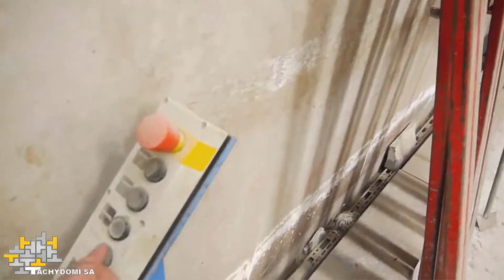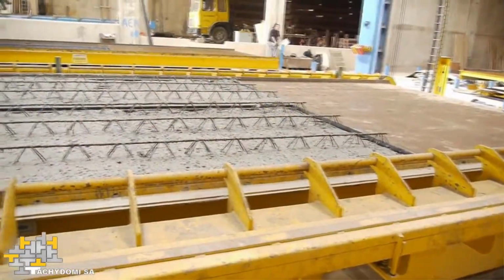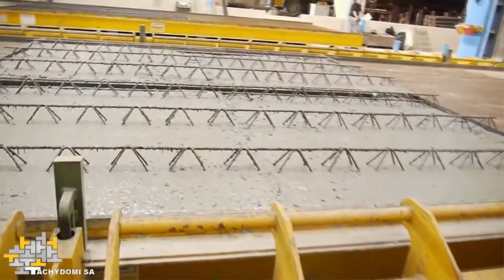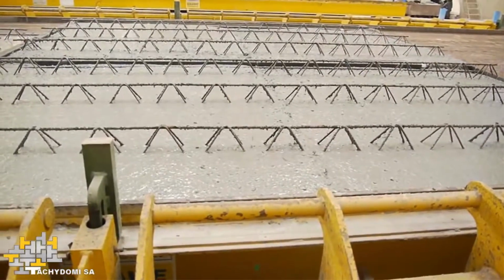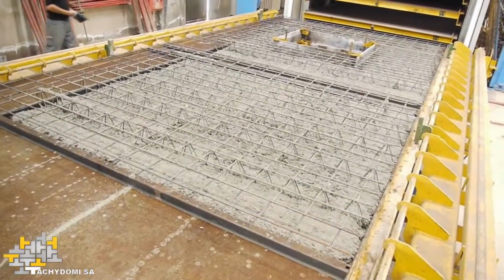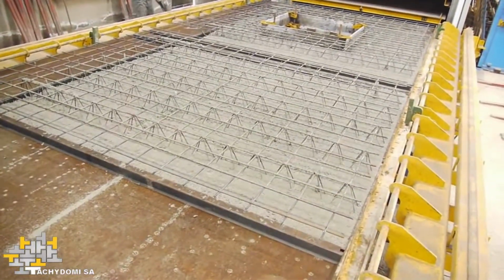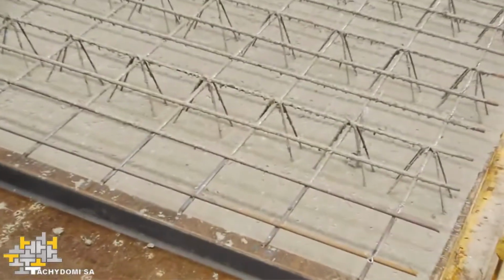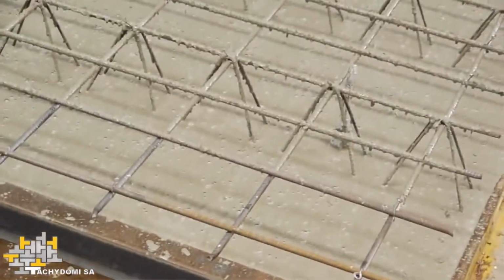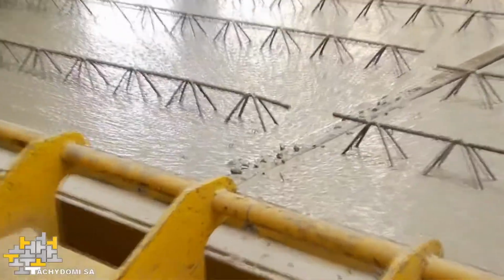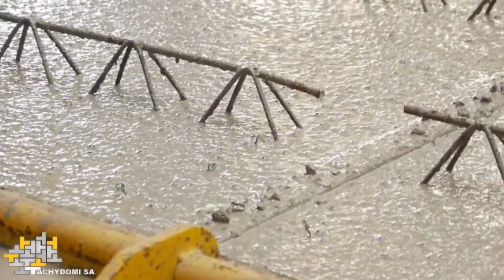Can you see now the difference in the way the concrete is from what it was when it was initially kept? The cement paste is just floating up. Okay? This is called laitance. What is floating on top is laitance. And this is the way you are expecting. That is the sign that your concrete has been fully compacted or vibrated.